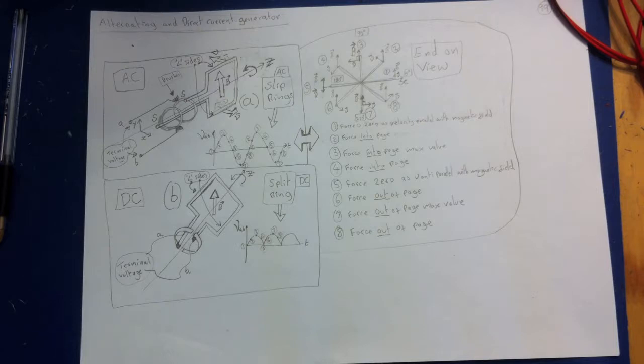We connect the loop to a split ring this time, or commutator, as in this diagram B. At angular positions where the EMF reverses, near theta equals 0 or 180, you can see that there's a split ring here. Now those leads are going to swap over, and it's going to continue to be positive. Whereas before it was going through because the rings are continuous, now they swap over, so you can see how that occurs. So you can generate a DC voltage with this.